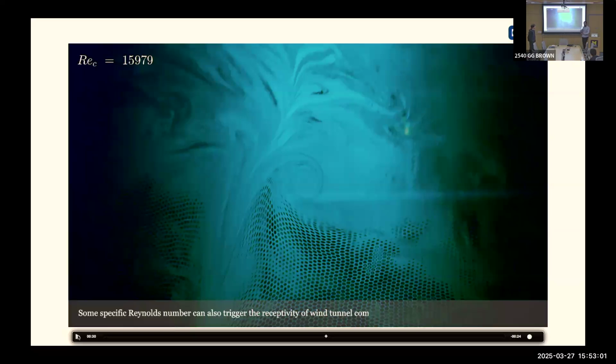And then when we look at the PIV, we can see this in the PIV too. So we avoid this Reynolds number for tests because this is not actually desirable. But whatever mixing stability thing happens normally, we just hit some condition where it doesn't mix. And then this has just been transported for 7 meters as it is until it hits the vortex, which then mixes it. So we are interested in just doing PIV on just that. And when I showed it to a colleague, they said that someone else had shown something like this, where you pass flow through a tube and it just remains like that forever. But it also says that our flows must be pretty laminar otherwise. So I guess if we want to do a laminar test, we should do it at this velocity. But that's what we think is going on here.